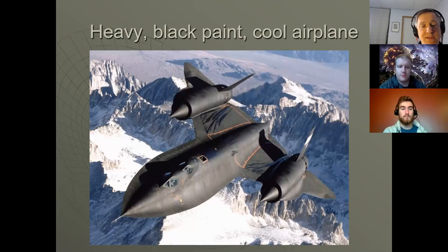What it's doing is it's emitting radiation. So this gets really hot as it travels through the air, but the air is very thin, so the convective heat transfer to the air is very low. There's no conductive heat transfer because the air density is so low. There's no mass transport. I mean, it could carry tons of water and jettison it and just kind of get rid of it that way, I suppose, but that's not practical because of the weight. And there's no endothermic reaction like a cooling gel in there because, again, you have a weight issue. So the best way it can get rid of energy is through convection and radiation. And again, convection doesn't work very well, even though it's traveling fast.